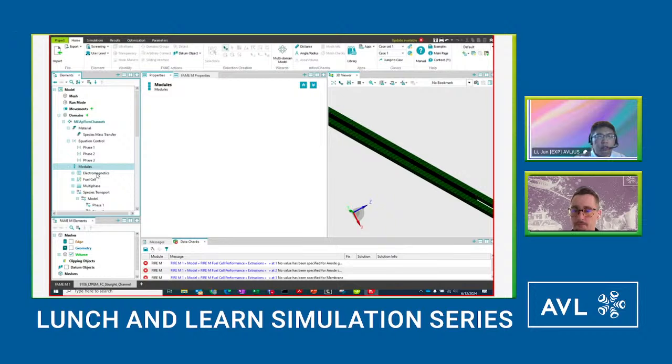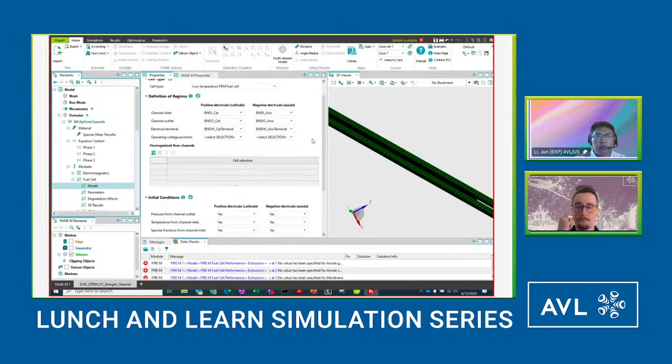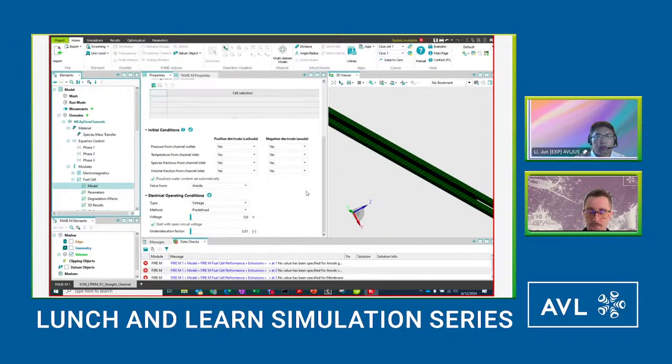We solve the potential in the GDL and the catalyst layer, and also the ionic current density in the membrane and also the catalyst layer. And then we have this fuel cell model, in which we specify where the channel is, where the terminal is, and then we specify the operating conditions. In this case, we use the voltage.